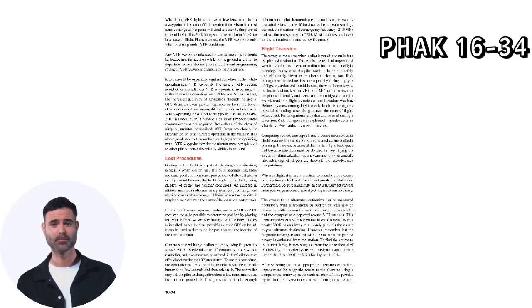Lost procedures. Getting lost in flight is a potentially dangerous situation, especially when low on fuel. If a pilot becomes lost, there are some good common sense procedures to follow. If a town or city cannot be seen, the first thing to do is climb, being mindful of traffic and weather conditions. An increase in altitude increases radio and navigation reception range and also increases radar coverage.